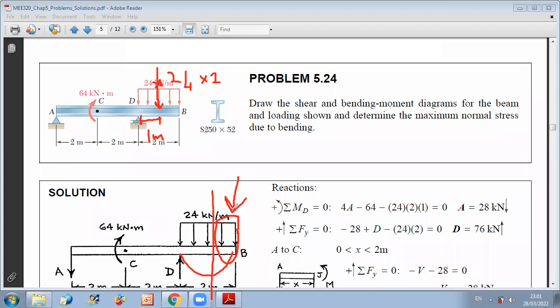After you do the cut, you reduce the distributed load, because we already discussed that whenever we compute internal forces, we cannot replace the distributed load by a concentrated force before the cut. We can do it after the cut, because it can help us into getting always external reactions.